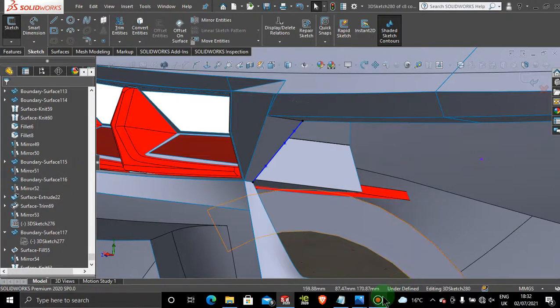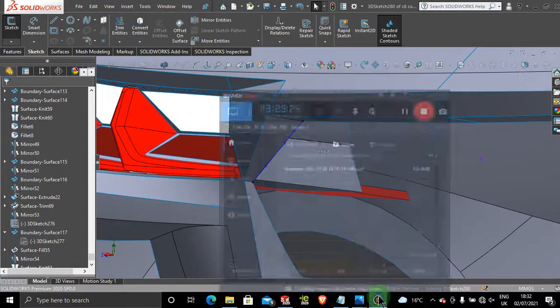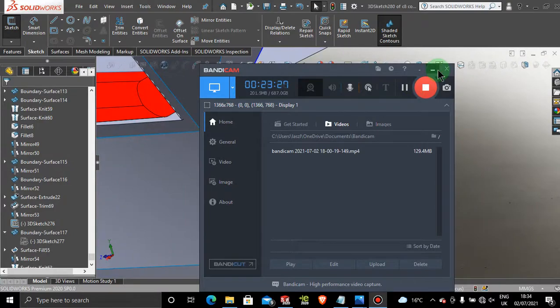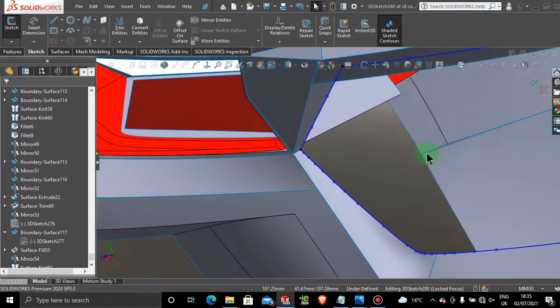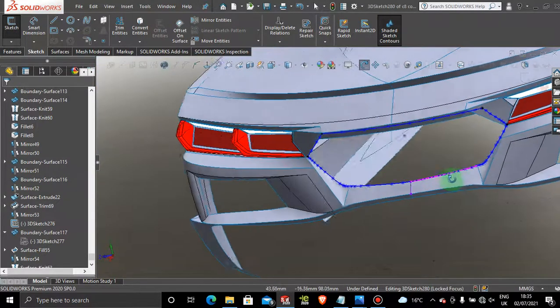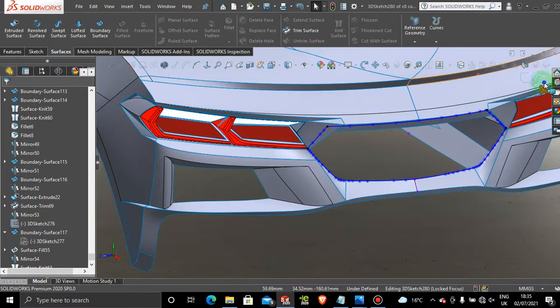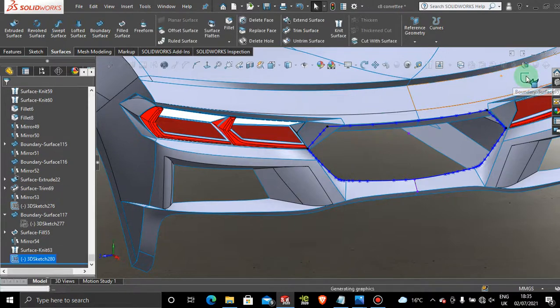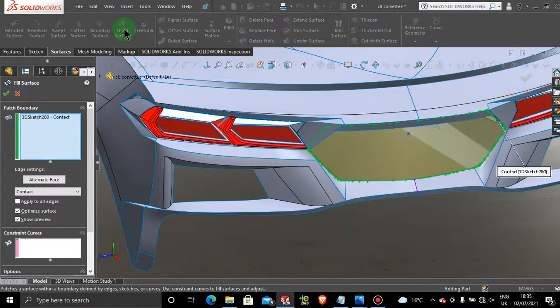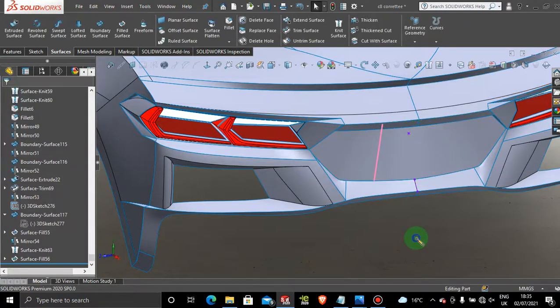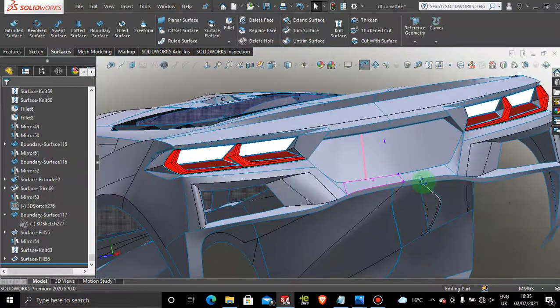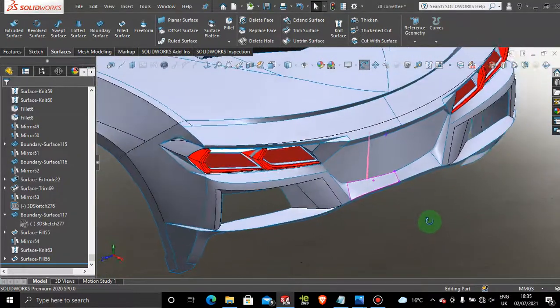And I see back when I made all these corner sketches. So once you added all these sketches all the way around those edges, exit the sketch, and then just jump to the surface, and that'll create a beautiful surface for us. And then there you go, and created that surface for us perfectly.